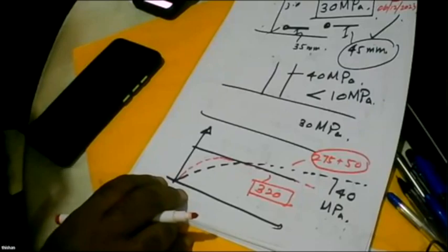Now you can see when you use fly ash based concrete, it's good to continue the curing for at least 14 days, so that over the 14 days all the tricalcium silicate will react and form a lot of calcium hydroxide and calcium silicate gel to create a strong concrete. Now fly ash can come into action and continue to react with the calcium hydroxide generated by the reaction, and then create a very dense and very strong concrete, and you target 30 megapascal in 28 days.